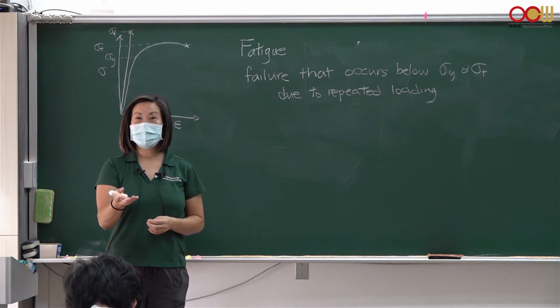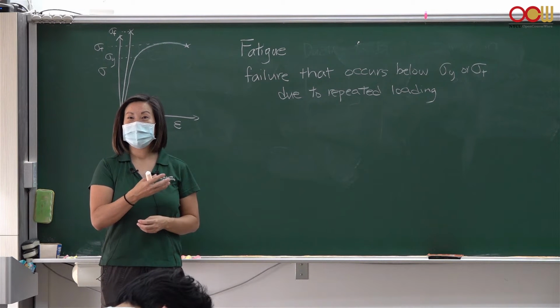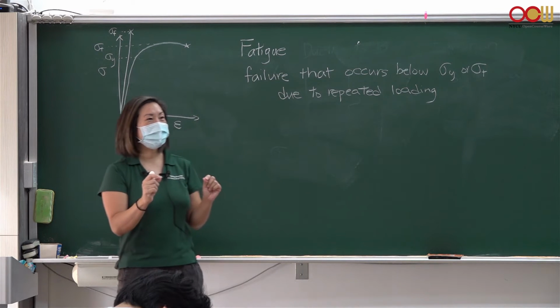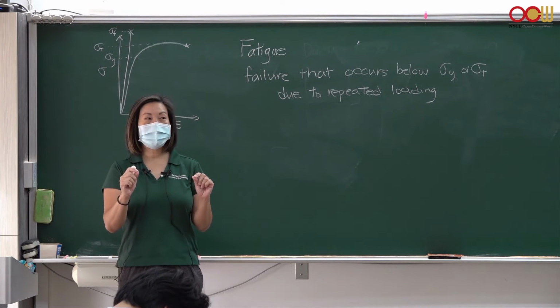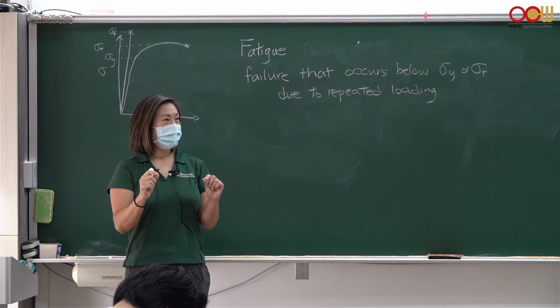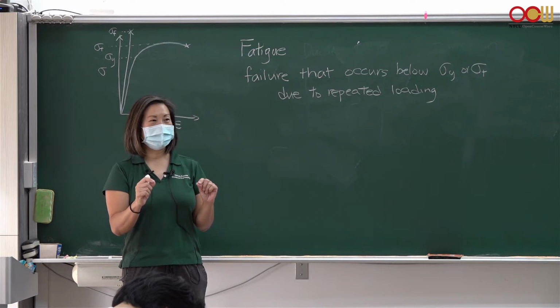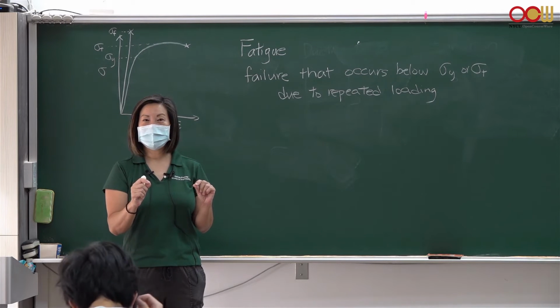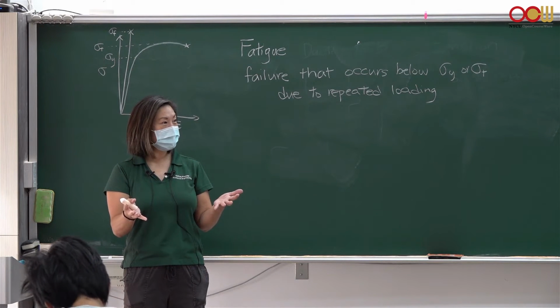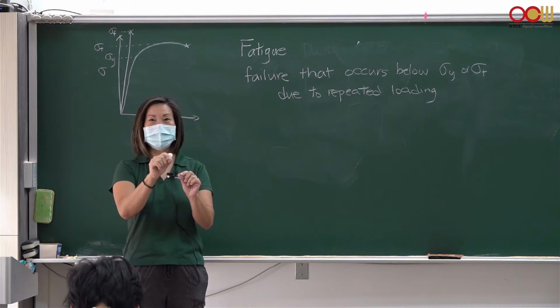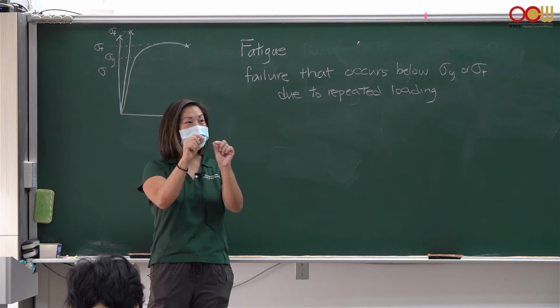Dislocation, moving to the bending point. So what you're doing when you bend the paper clip is that you're causing permanent deformation, right? You're deforming the material. How do materials deform permanently in a ductile material? By dislocation movement. Right?